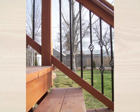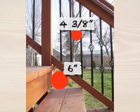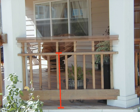Looking at a stair guard as an example, this is the region that cannot allow the passage of a 4 3/8-inch sphere. The triangular region made up by the riser, tread, and the bottom of the guard cannot allow a 6-inch sphere to pass through. And just to complicate things, the stair riser cannot allow the passage of a 4-inch sphere. These opening limitations are only for the area up to the 36-inch height. Guards taller than that can be designed with unrestricted openings above that height.